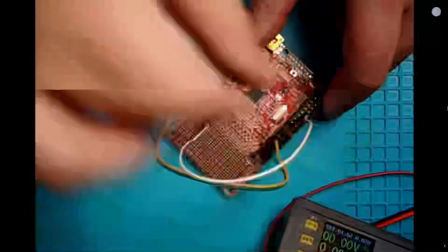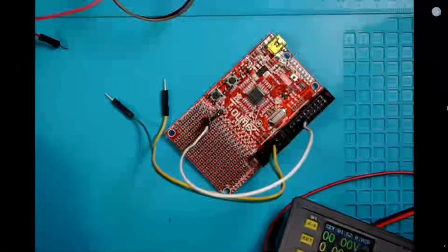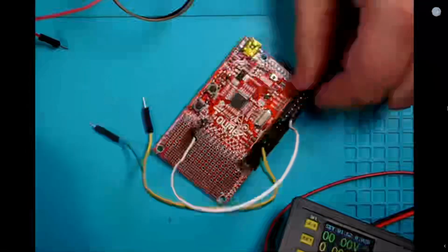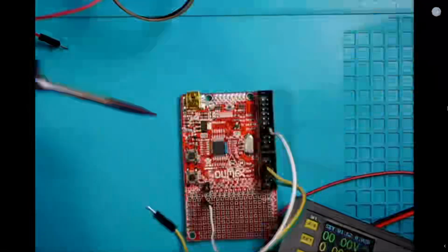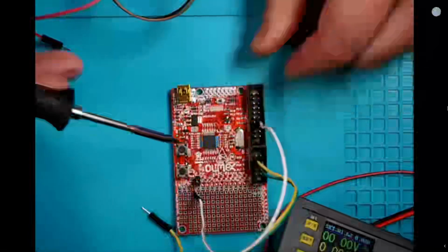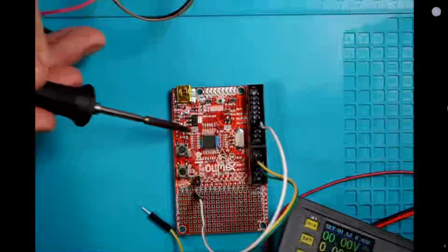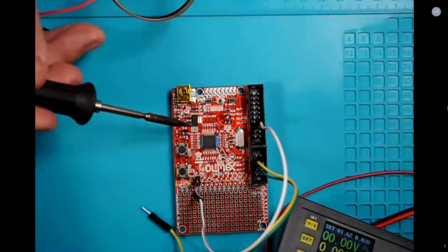If you're asking me, the easiest way to do it is always just to use 2 irons for removing the capacitors. And after we do that, we have these shunt pads, which we have on this board right here. You'll see one's labeled 3.3 volt IO, and the other one's labeled 3.3 volt core. So these are 2 pads.